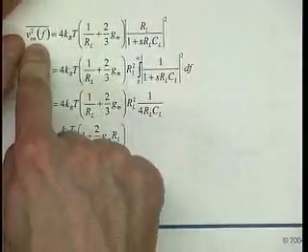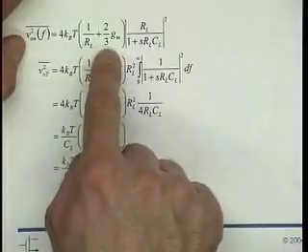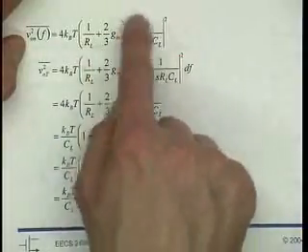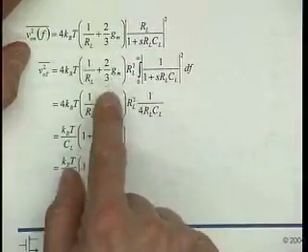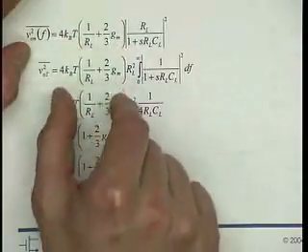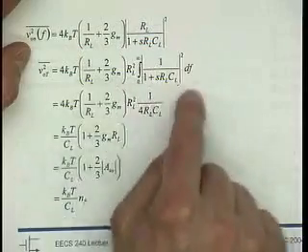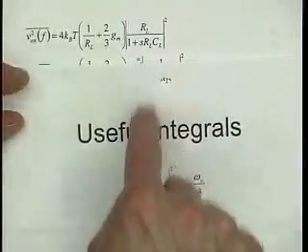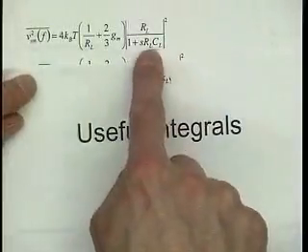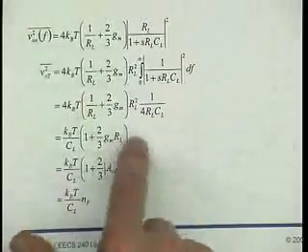This is the noise spectral density at the output that we had calculated before. I put 2/3 for gamma, and here is the transfer function. Then we have to integrate this over all frequencies. This part here is independent of frequency, so I can pull it out, and the RL also. And then I get this integral here. I go to this table and find that, lo and behold, this integral looks just about the same as this one, if I make omega 0 equal to 1 over RLCL, and substitute and so on.